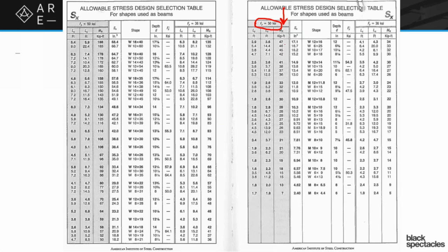On the right-hand side, you see that we max out at 47, so we're going to keep going and come down to the bottom of the left-hand side, and we see 50 right here at the bottom, and I just drew right over top of it. But we do see 50 show up, so we at least know that this 8 by 21 beam will satisfy our load. But one of the things with the beam chart here is you'll notice that the beam sizes above it, some of them are lighter. So while this 8 by 21 works, it's not the most efficient shape. This top one actually is an M shape, so we're just going to jump to the one right above it. But we get a 12 by 19 is the lightest beam that hits that 50K.